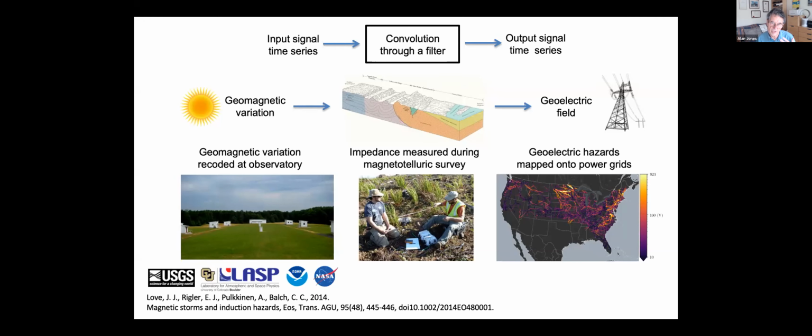But the transfer function itself was derived assuming a uniform plane wave field, and yet your interest, of course, is in highly non-uniform sources, and that transfer function will change as the sources change. In fact, if you're under a highly non-uniform source field, you'll get much less electric field than in the uniform case.